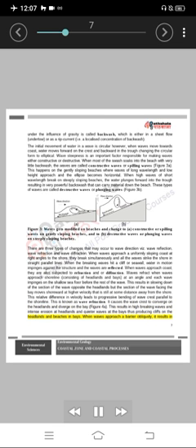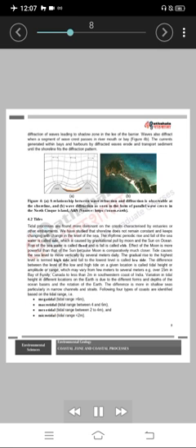When waves approach a barrier obliquely, it results in diffraction of waves leading to shadow zone in the lee of the barrier. Waves also diffract when a segment of wave crest passes in river mouth or bay, figure 4b. The currents generated within bays and harbors by diffracted waves erode and transport sediment until the shoreline fits the diffraction pattern.